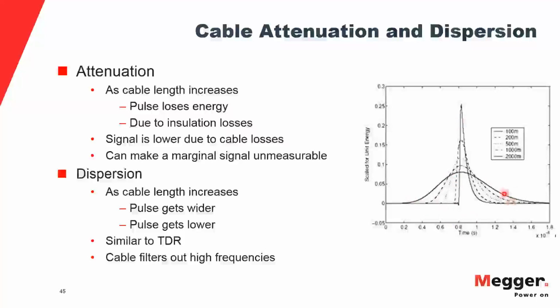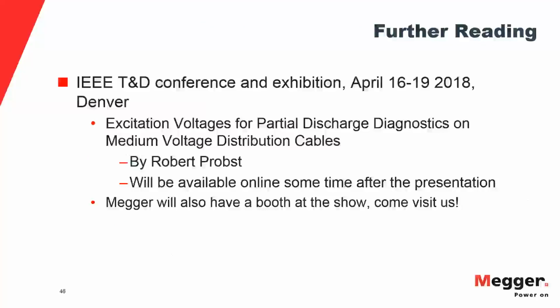We have our integrated test vans like our Centrix 2.0 and our Centrix City. These take our cable testing and fault locating and combine it into one integrated solution. Has a lot of safety interlocks. It's a highly customizable unit. And finally, we have our DAC 30. This is up to 30 kV peak. It's damped AC only, which makes it ideal for PD diagnostics. What is unique about this one is it's completely enclosed. There's no external coupler with this, like you see on these other units. Everything you need is inside this case, and it's very small and lightweight too.